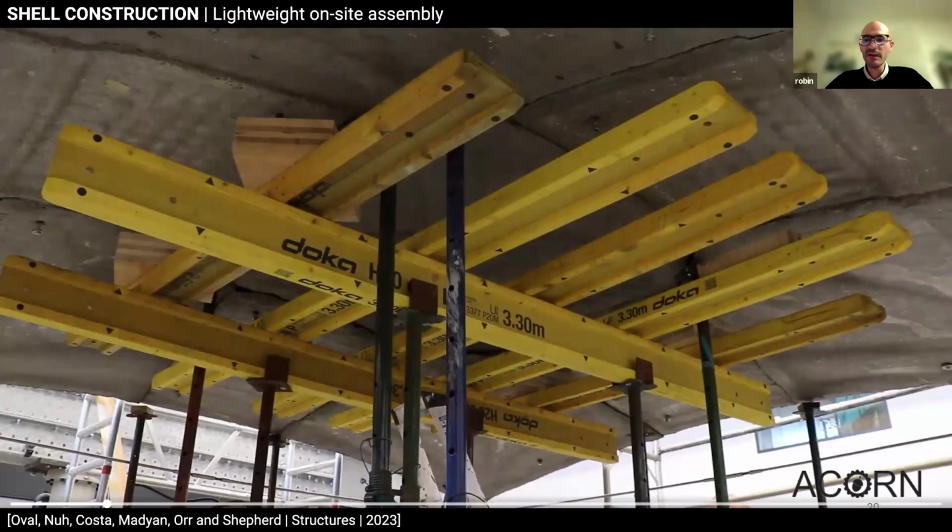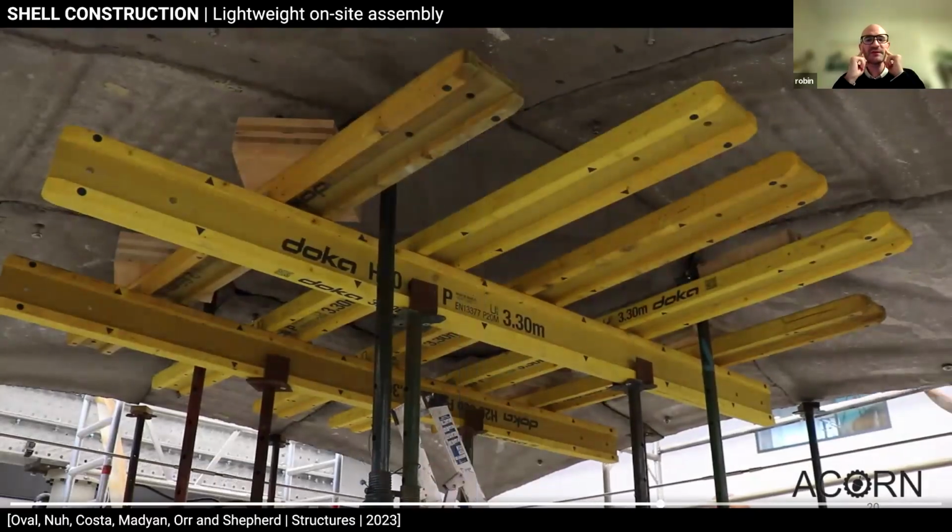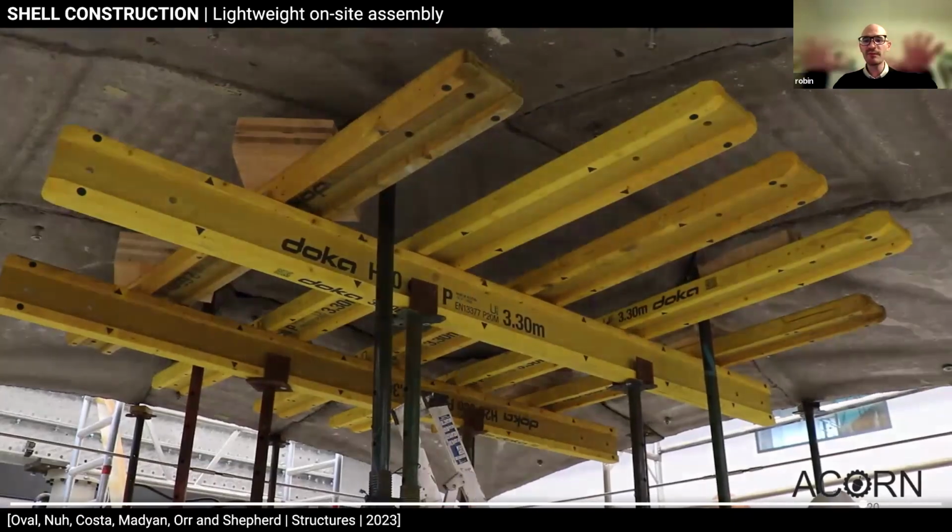Then for assembly, so here we had some kind of scaffold or platform for safety and accessibility, but eventually we just put these 9 modules on these telescopic props. And then what we did, we put them a bit higher than the final position.